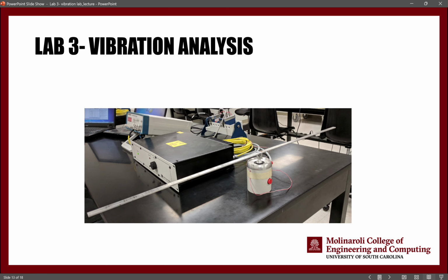Let's talk about the lab itself. The lab is going to look something like this. You do need a computer to read data off of a strain gauge that is either installed here or installed at the end of the beam. We have a shaker, which is holding the beam in the middle. It's connected to an amplifier, a signal express system. So this part, I have simplified this semester. You're going to see a different signal generator. It's very simple, just read the frequencies and add the frequencies, to make things simpler for you guys and a little more reliable.